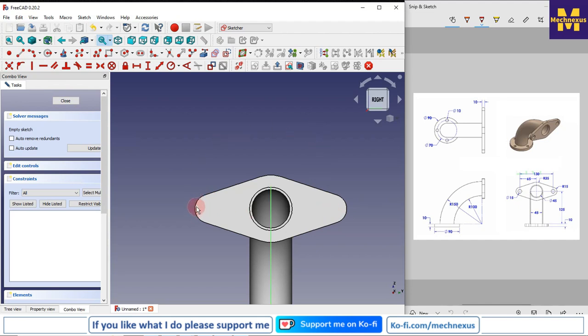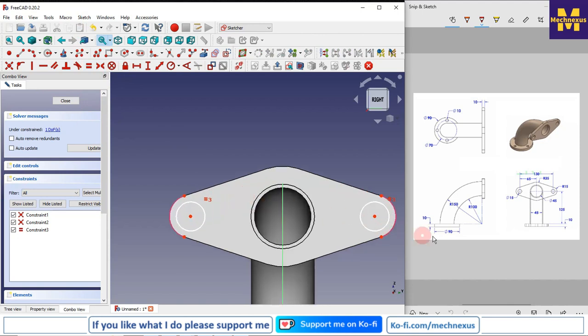Now I will project these two arcs. I will select this one and this one, and then I will create a circle and I will make it equal. The diameter is 15, so I will select this and I will give it 15.